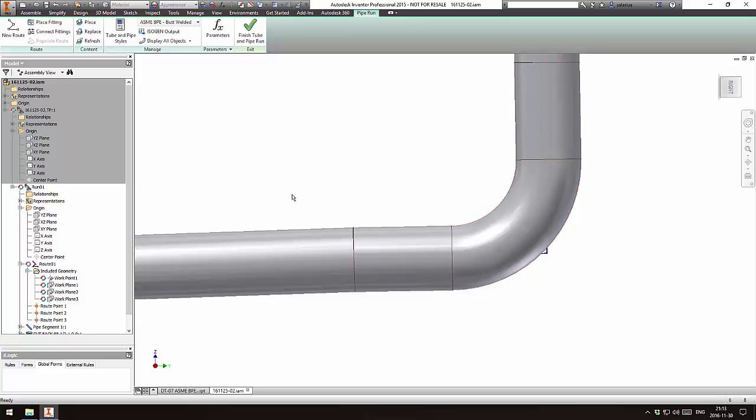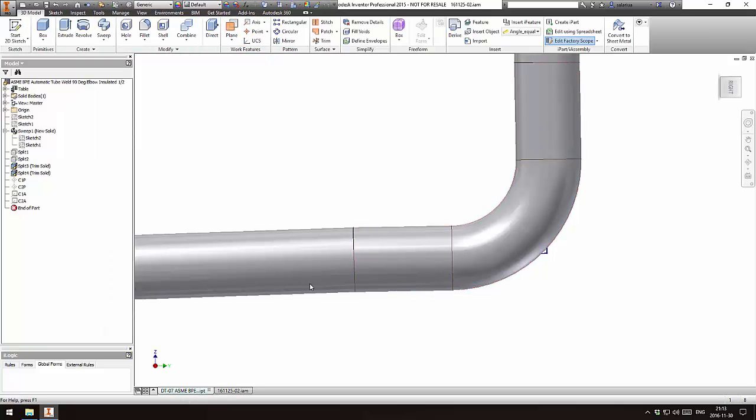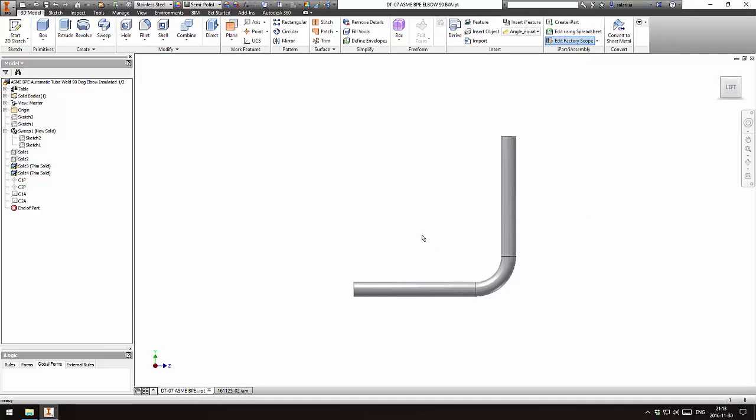Anyway, what he really wanted was, he said, no, you got it all wrong. I am cutting back the length of the standard elbow, but we don't cut it at an angle. What we do is what everybody does really, because to buy an 88 or 92 degree elbow is very expensive. So what we tend to do is take a 90 degree one and bend it 2 degrees in or out depending on where you need it.